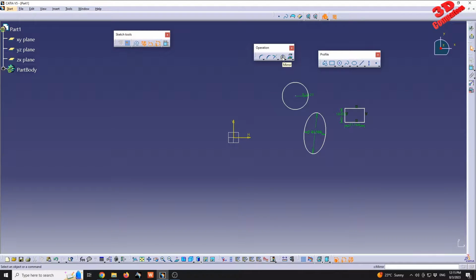I will start by using the mirror feature. We can activate it by clicking on that icon. If you read to the left of the screen, we see that we have to select the sets of elements to be duplicated by symmetry. I can click on an element like this, but as soon as I click on one, we are prompted to select the line or axis for which the elements will remain equidistant. In this case, I will select the vertical axis. And we're going to see that the circle will be mirrored along the vertical axis.